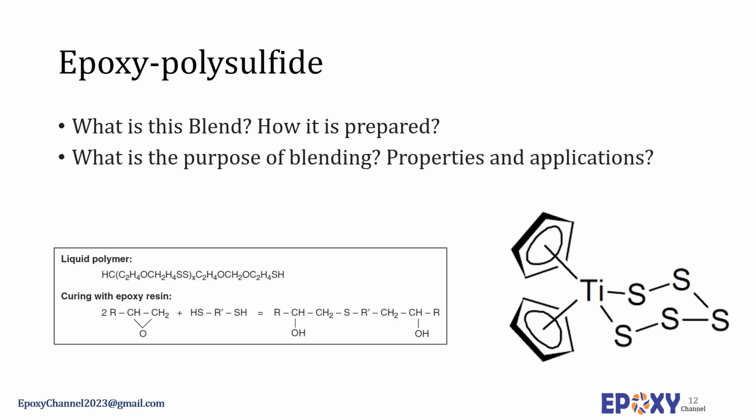Suitable curatives for the polysulfide epoxy reactions include liquid aliphatic amines, adducts, solid amine adducts, liquid cycloaliphatic amines, liquid amidoamines, liquid aromatic amines, polyamides, and tertiary amines. Primary and secondary amines are preferred for thermal stability and low temperature performance. Not all amines are completely compatible with polysulfide resins. The incompatible amines may require a 3-part adhesive system.